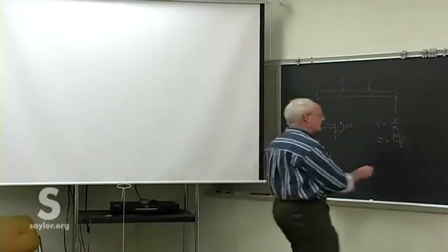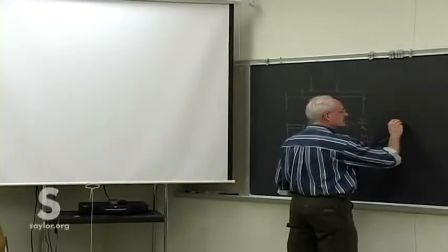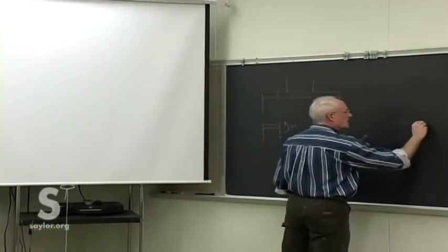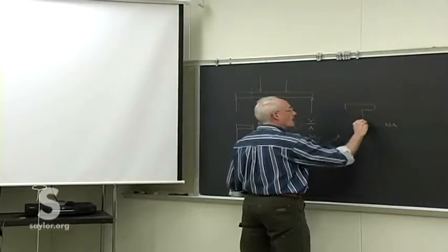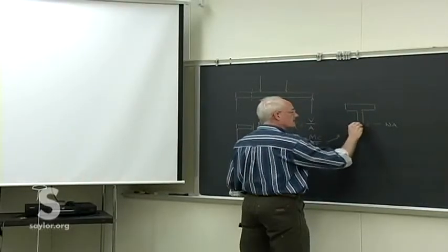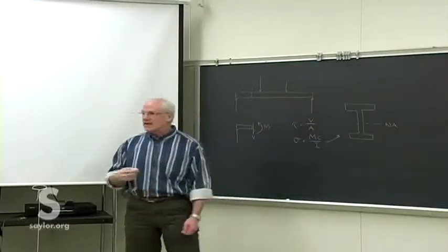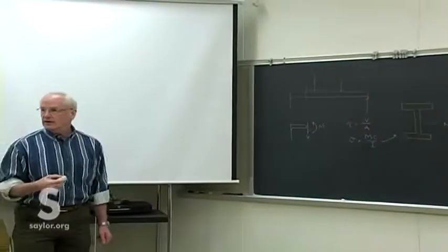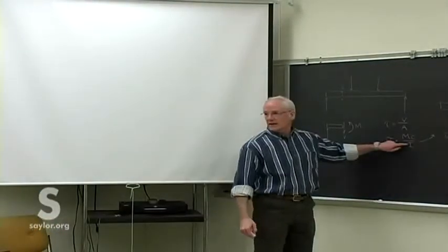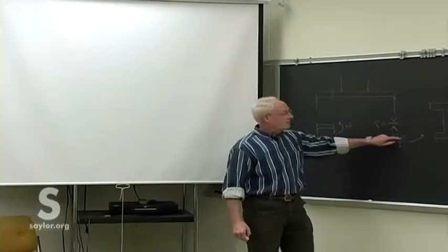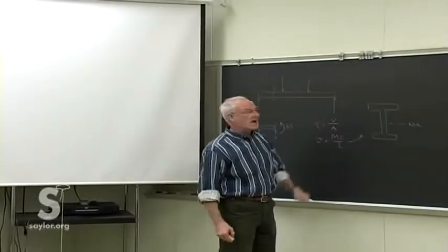Basically what we are finding out from there is that whatever the cross-section, we needed as much area away from the neutral axis as was practical. And that's why I-beams are so very useful in construction purposes, because they have a very, very big I, because of so much of this area that's away from the neutral axis.